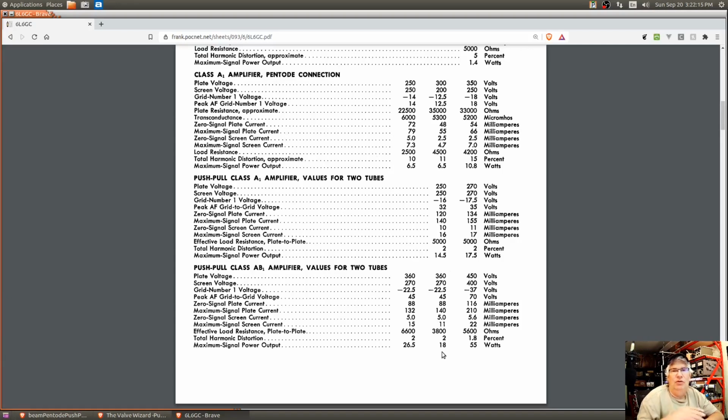With two different output transformers, the turns ratios are going to be a little bit different, so the reflected impedance is going to be different. What should you expect if you have a turns ratio of, I think the first one is 29, maybe it's 27, and the other one is something else? This is what you should expect from a distortion characteristic and power output if you choose that impedance level, but that's just everything being equal. You get to choose, and you can estimate your power output. But the viewer's question is, why are column 1 and column 3 different? That's what we're going to talk about.